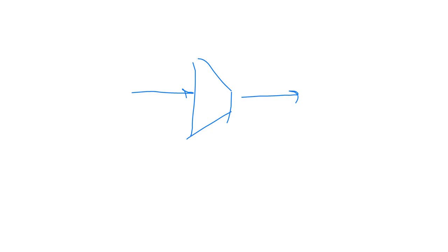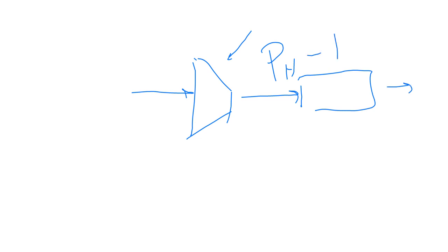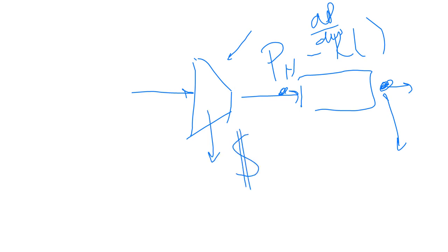So if I have a compressor for a gas, and a compressor is a seriously expensive piece of equipment, and I have to operate that with a very high pressure at the inlet to my reactor in order to overcome my Ergun equation there with the factors, okay? The pressure drop over my reactor. So I need a very high pressure there so that the outlet pressure does not fall below a certain minimum value. So that will be a requirement. Not only do I have to pay for that compressor initially, I will also have to pay the electricity bill every month.